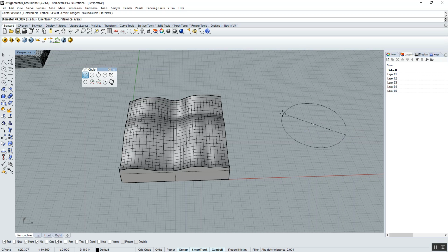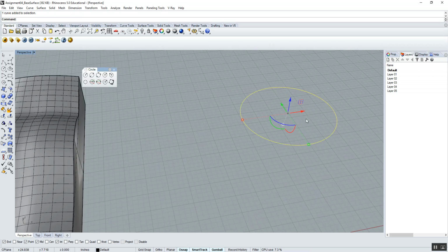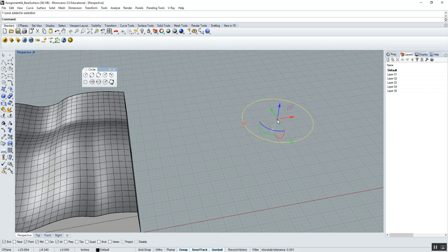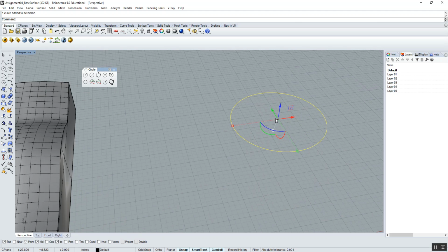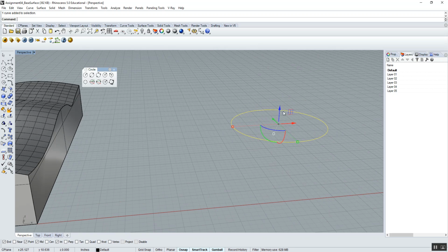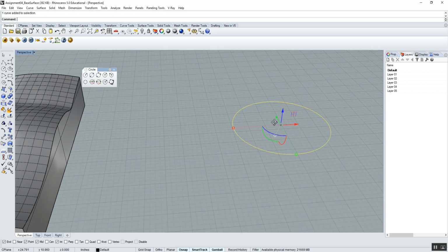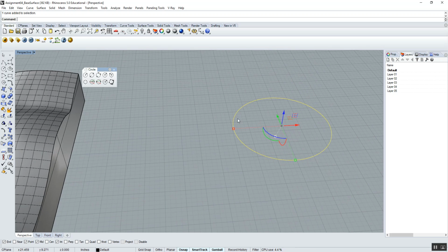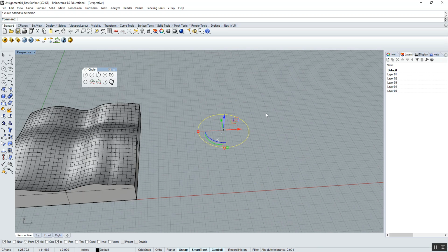So I can click anywhere I want, and I can manually select the actual radius, or I can click a distance in the upper left. I'm going to click on the plane there, and now I made a circle. This circle is considered a CNR, center, normal, and radius, meaning that I dictated where the center point was, the axis or the plane that it was on, the axis it's perpendicular to or normal to, and the radius itself. So I can do something similar in Grasshopper.